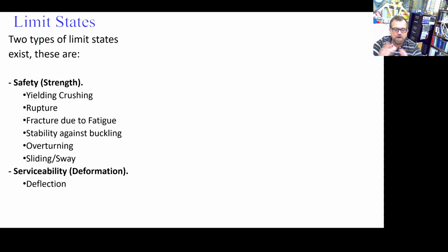Yes. So for example, if you have a roof and that roof is deflected, there are different considerations within the specification. If it's not plaster, and you have a ceiling covering that roof, it might be deflected, you don't see it, it's within parameters, nobody notices it, and nothing happens.